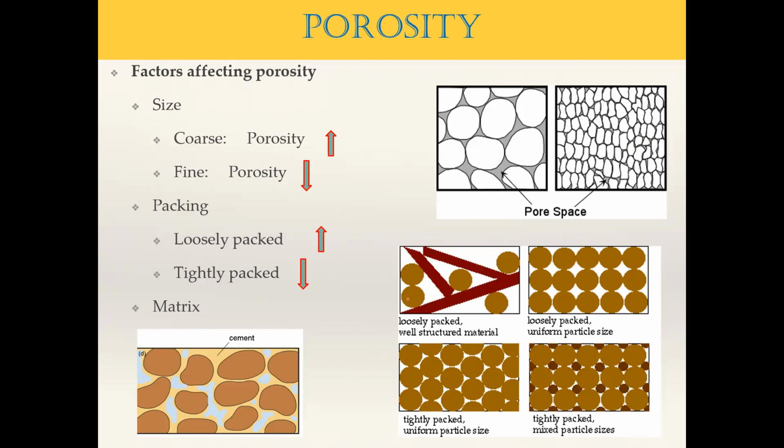Right. So what are the factors affecting the ability to store water and the ability to transmit water? In other words, what are the factors that affect the porosity and the hydraulic conductivity? Now, in general, I want to emphasize the term in general, okay, not always. In general, when the particle size is higher, the porosity becomes higher.